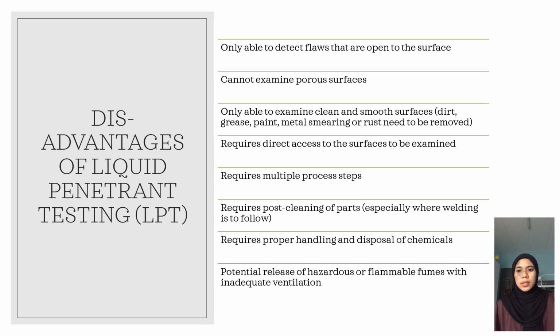It requires direct access to the surface to be examined. It requires multiple process steps and post-cleaning of the part. It requires proper handling and disposal of chemicals, and there is potential release of hazardous or flammable fumes with inadequate ventilation. These are also disadvantages of liquid penetrant testing.